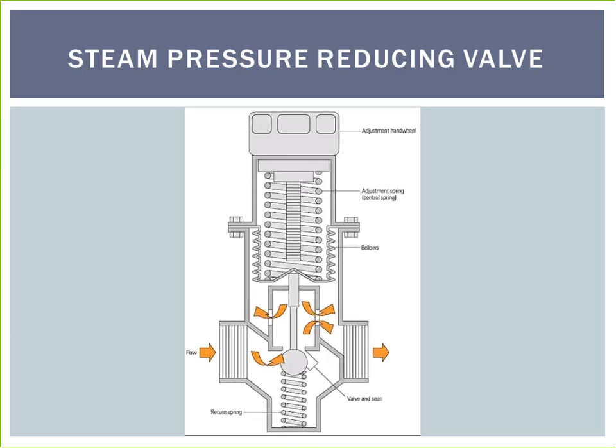For the most basic pressure reduction, it is possible to simply use a conventional globe valve in a fixed, partly open position, or by inserting an orifice plate into the flow of steam. However, any fluctuation in flow rate would be accompanied by a corresponding fluctuation in pressure. To avoid such circumstances, pressure-reducing valves can be used to provide precise control of downstream pressure.